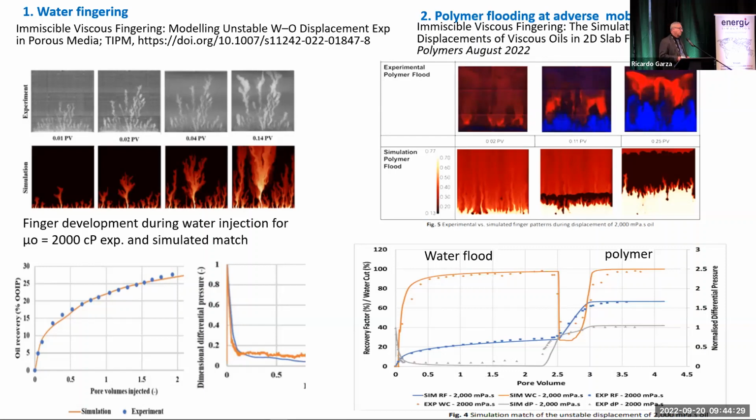Blue color is the increased water saturation. So by injecting polymer, we see that we are crossing oil into the water channels already being made. So we have a cross flow into the channels, and that's the least resistant pathway. It would rather displace water at 1 centipoise than move forward the oil at 2000 centipoise over the whole length.